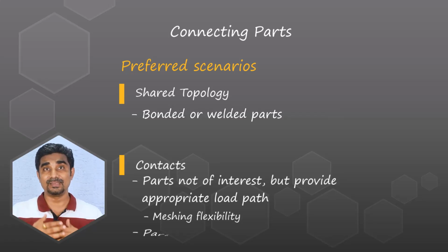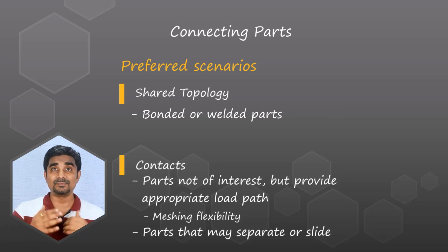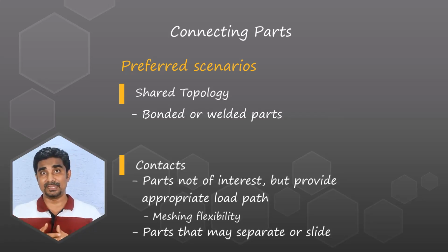It is also worth remembering that if the parts may have the ability to separate or slide with respect to each other, then contact should be used for connecting parts. I hope this video will help you in selecting the appropriate method for connecting the parts in the assembly.